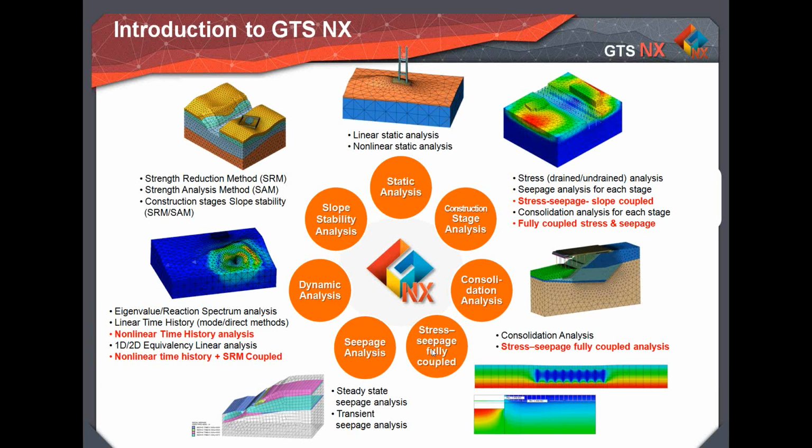So if you have, for example, a dam or a levee, and you want to do your seepage analysis in combination with your slope stability analysis, you can do that very simply. And then you can model multiple transient stages or steady state stages for rapid drawdown or changes in water level. And then dynamic analysis if you're doing any sort of seismic analysis, for example, if you're doing maybe earthquake loading or dynamic loading.